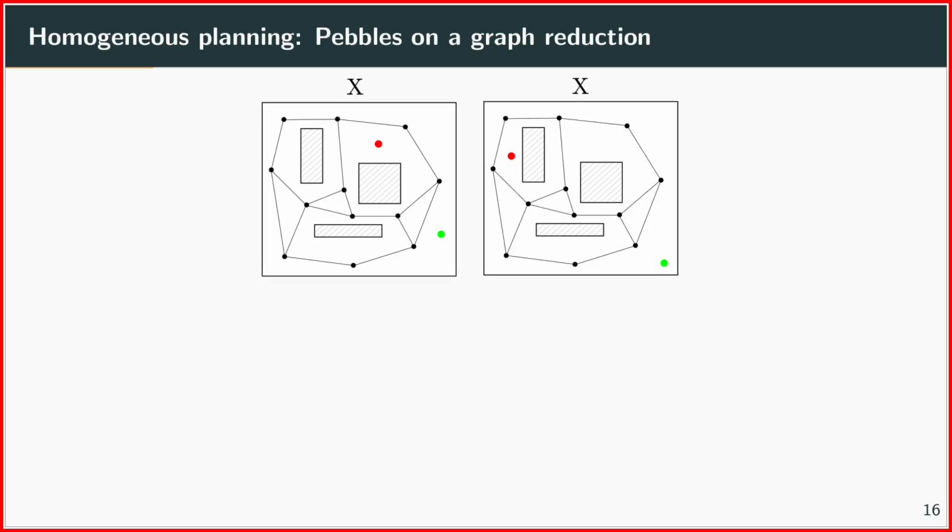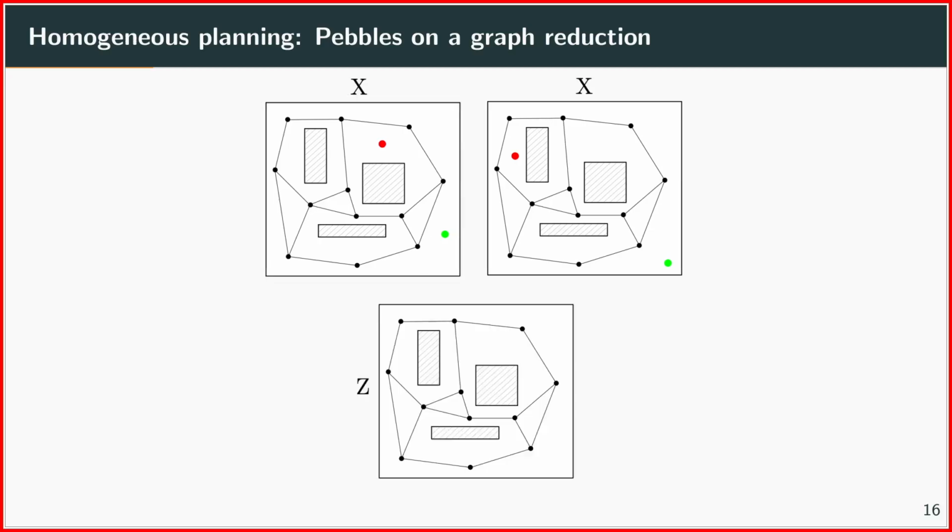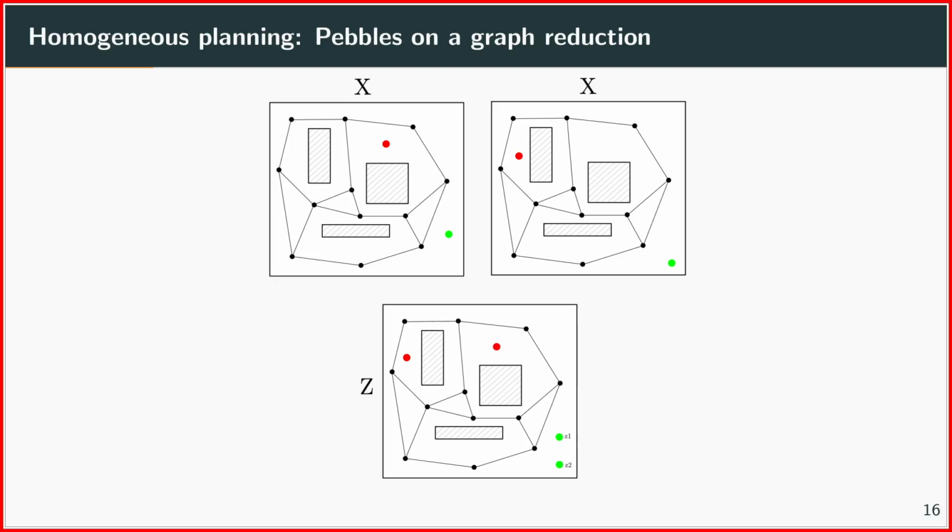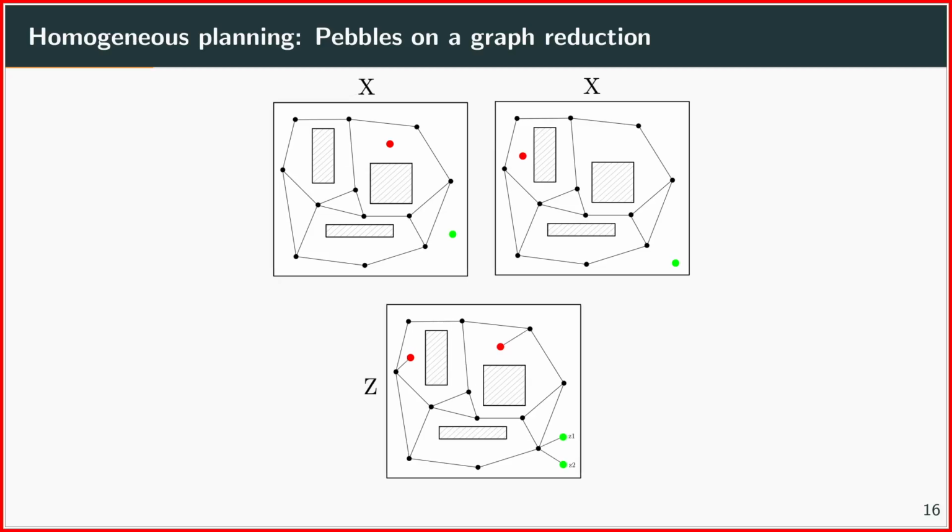And if you have 100 robots, then you can theoretically copy-paste it into all the state spaces of the other robots. What this enables you to do is take a new state space, which I call Z, copy-paste this roadmap into it, and also copy-paste the start configurations and the goal configurations of your individual robots. And then you connect them to the roadmap. This is very similar to what you did with the probabilistic roadmap approach, but this time you connect multiple robots to this roadmap.